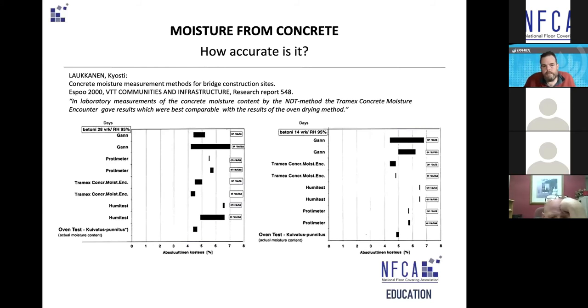Now there's a whole variety of different screeds and everything else that you can get, but the majority of what you're testing with that meter is the moisture. It's sending a signal from the surface down into the concrete, and you are measuring mostly the moisture, because it's an impedance test. To what depth is it accurate? About the first top inch of the concrete, which is where you're bonding to.